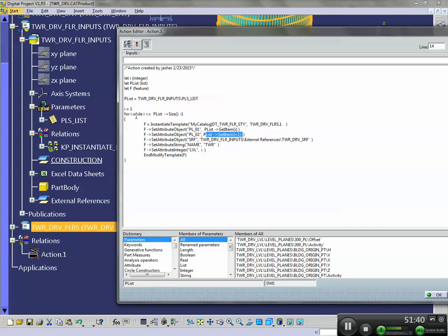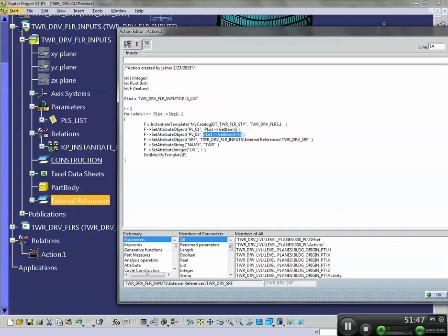When I equals 2, plane list now equals what plane list plus 1 used to equal on the previous iteration. So now plane list get item 1 is the second plane. Plane list get item I plus 1 is the third plane. So every time I iterate through, I equals I plus 1, I'm grabbing one plane for the bottom plane, and then the plane above it, the next plane in the list, for the top plane.